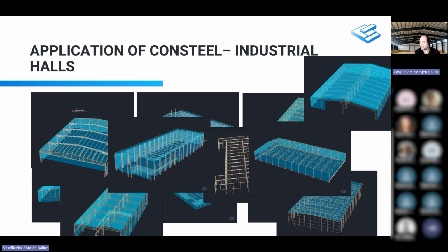On the other hand, if you see any of those examples which I have on the screen, then you will see structures here which are really light, made of slender elements, and very often they are stabilized by not very strong secondary elements. It might be a decision of the engineer to utilize these secondary elements of stabilization or not, or even more exotically use the sheeting, trapezoidal deck, sandwich panels, or others as stabilization or not. It's always a continuous debate whether this is a good idea to utilize these elements or not. I don't want to be the judge. We are just willing to offer a software which can do this task.